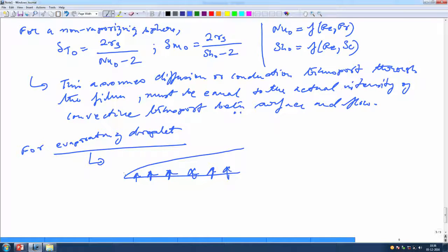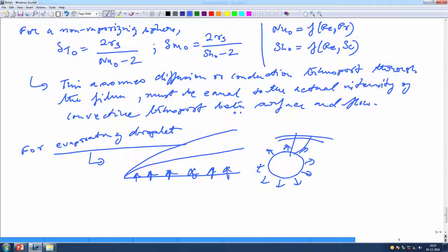What happens with that? The boundary layer actually gets extended, right. So, there is a thickening of the laminar boundary layer, so to say. So, imagine the same thing for a droplet, where vapors are being vented out because of the evaporation rate, right. If there is a boundary layer that existed on the liquid surface, that boundary layer usually is extended or becomes thicker. Okay.